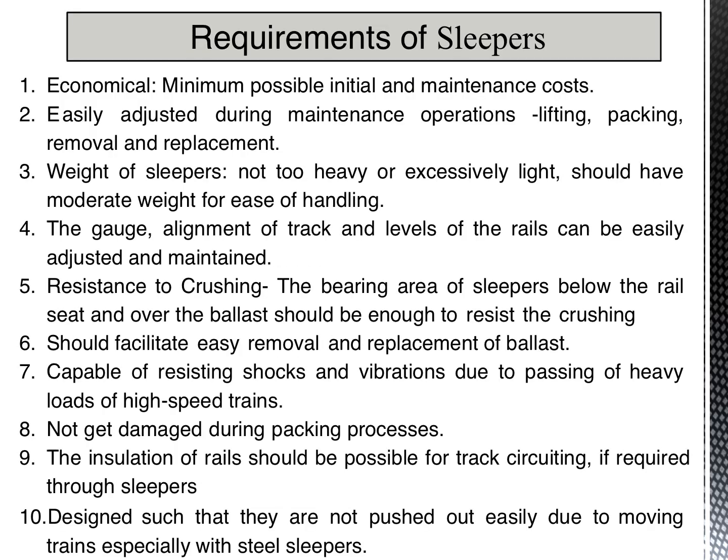Next, what are the requirements of an ideal sleeper? The first requirement is that it must be economical, meaning the sleeper used should have minimum initial as well as maintenance cost. The second requirement is that the fitting of the sleeper should be such that it can be easily adjusted during maintenance operations, such as lifting, packing, removal and replacement.